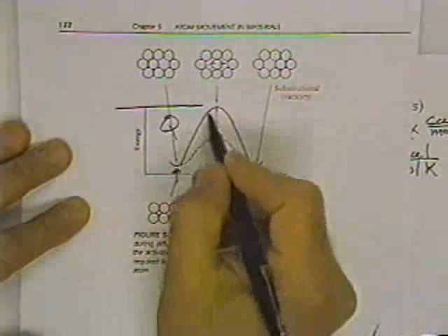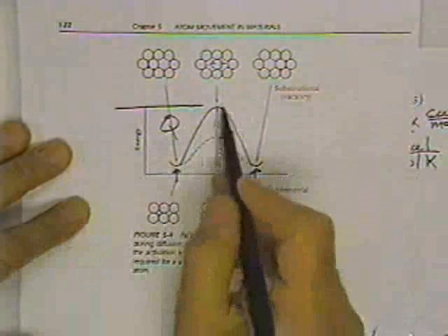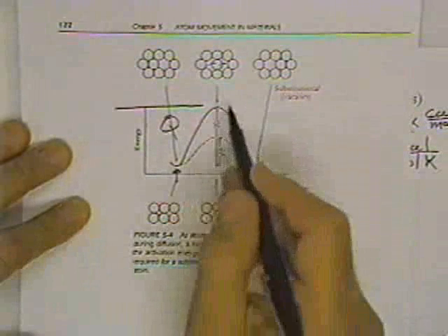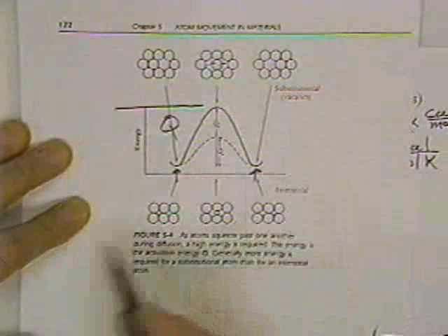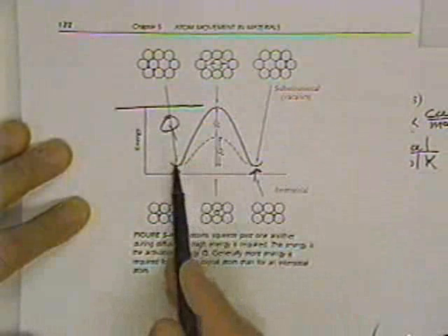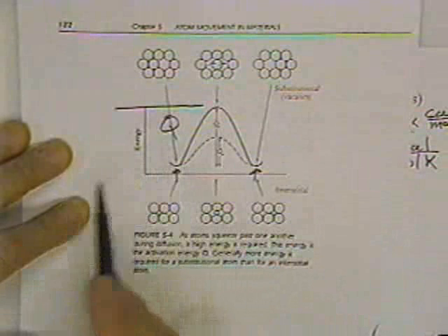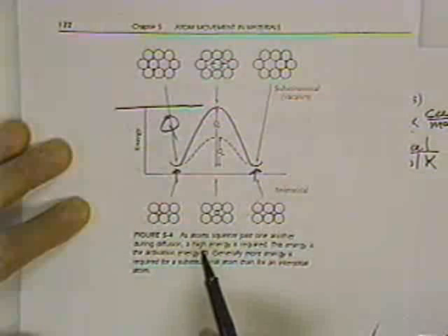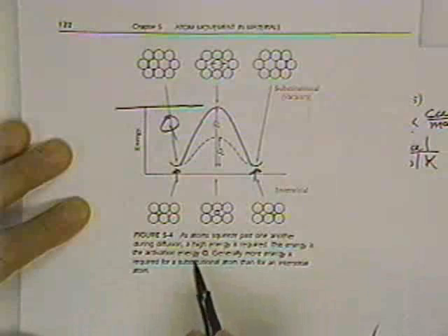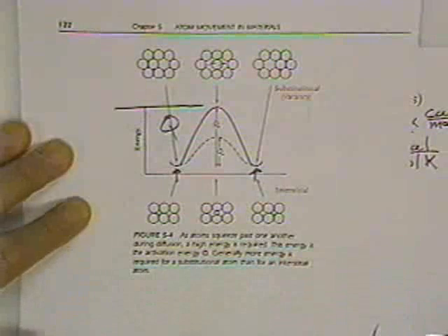Well, what a thrill coming down. So this activation energy is the energy you need to climb up the hill. Once you get to the top of the hill, it just falls on down. As temperature increases, it becomes easier for the process to go. It's exponential, so it's going to be a very significant function of the temperature.